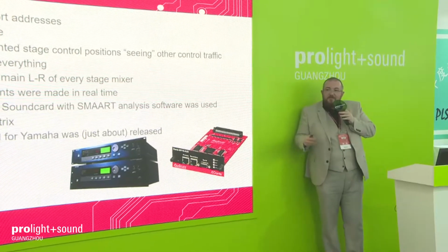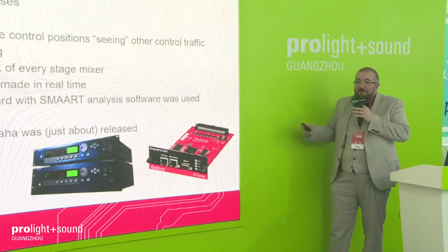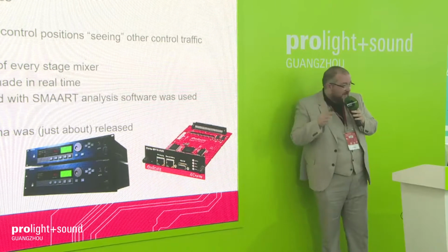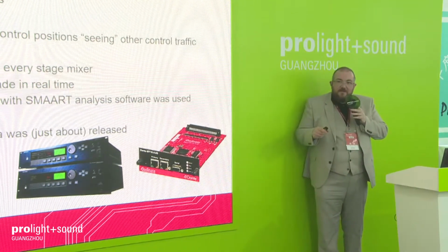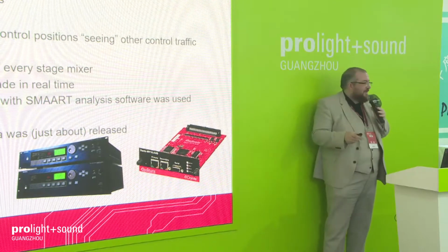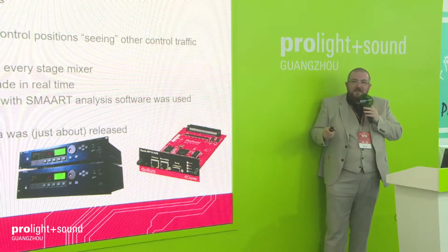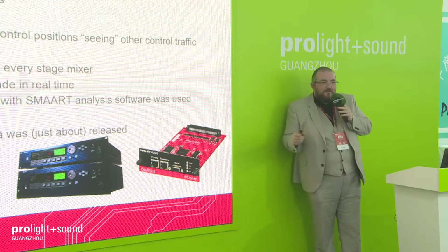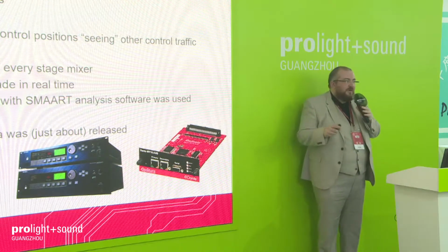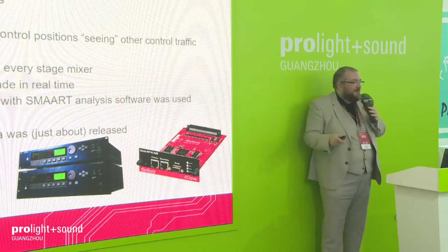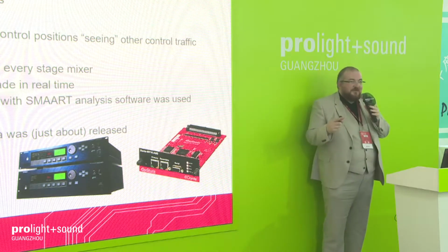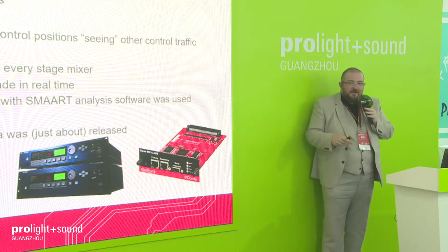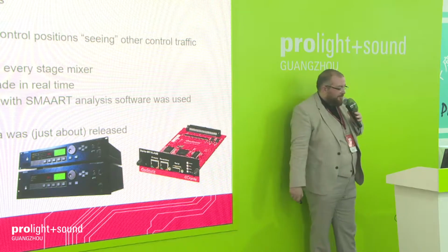The following year we improved upon this again. This is always an experimental thing, and we used the virtual sound card with the smart software to do the analysis of each stage. So we were able to take coherence measurements from each stage to work out which was the major contributing factor at our measurement points by checking the coherence and delay between a stage and what was being measured. So again, a massive improvement there.